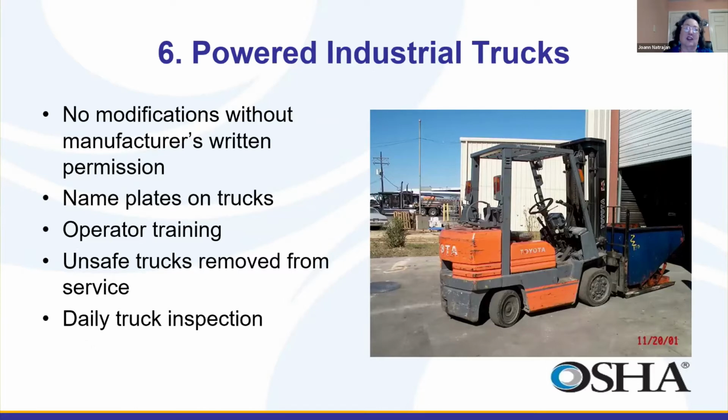Powered industrial trucks. Here, a big one that we find is people like to modify trucks. They like to add funny things on them for specific tasks. And what happens is when you do that, you change the center of gravity of the truck.